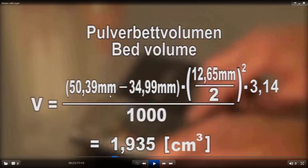If you subtract this, you will get the height of a cement sample, or the depth of a cement sample in the cell. This is the inner diameter. By this formula you will get the cross-sectional area multiplied by height. You will get the volume. This is the conversion factor.